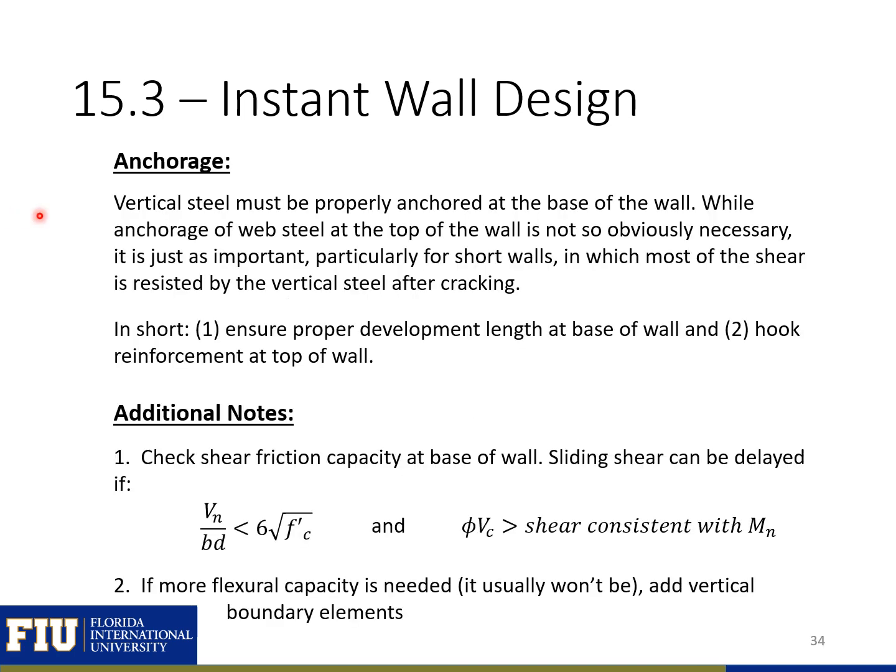Next, a few other notes. We need to make sure that all of our reinforcement is properly anchored. To do this, we need to ensure proper development of the reinforcement in the base of the wall, and we need to make sure that we're hooking the reinforcement at the top of the wall. This makes sure that we have development of the reinforcement at the bottom and the top.